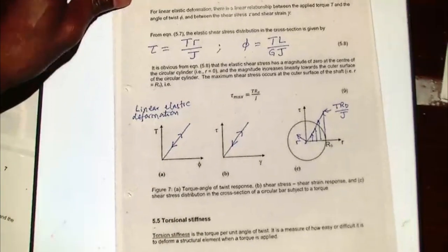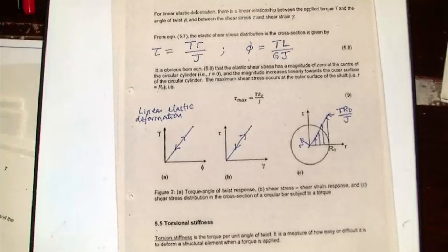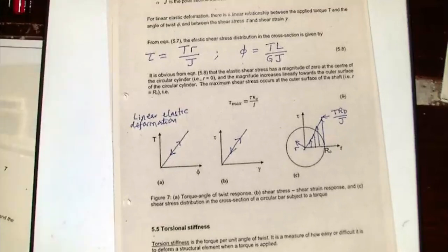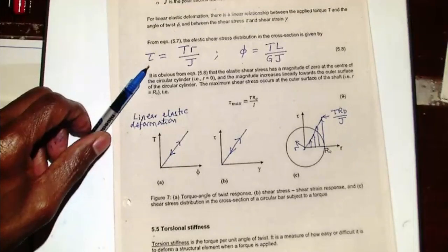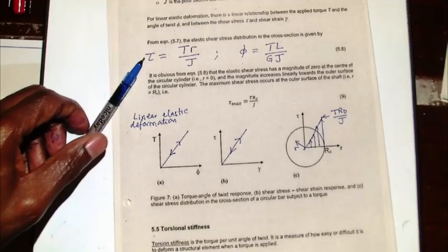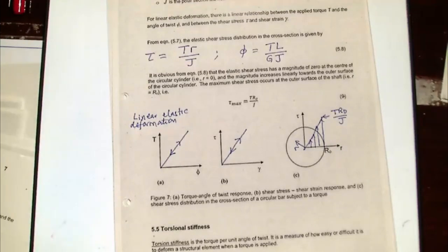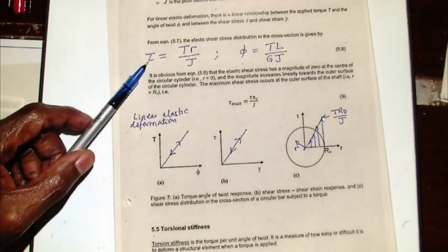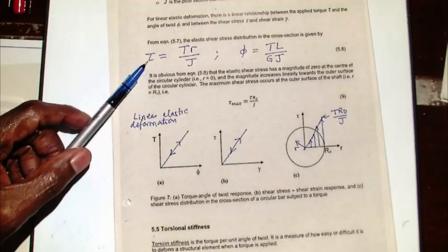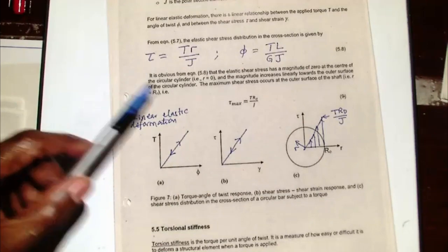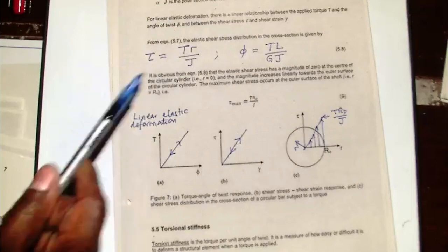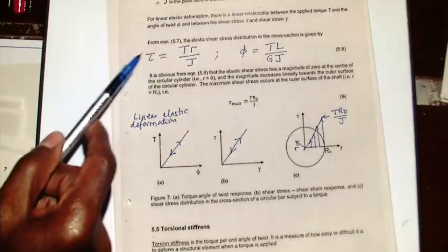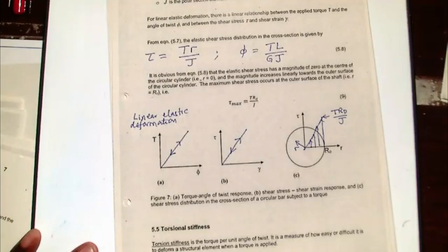We've already discussed designing for strength. Sometimes you design for stiffness. They are two completely different things. If you are designing for strength, then you want to make sure that this shear stress is below a given value for whatever material you are dealing with, based on the type of material. Steel, for example, will have a maximum shear stress it can sustain before it breaks. A simple concrete material will also have a maximum shear stress it can sustain before it breaks. You can then choose the load you can apply to make sure that the shear stress does not get to that value. That is designing for strength.